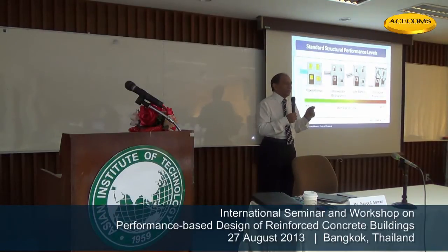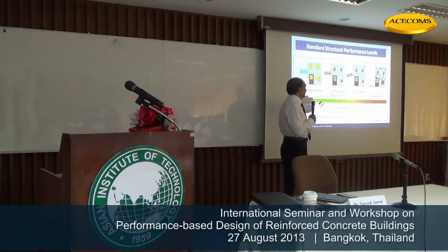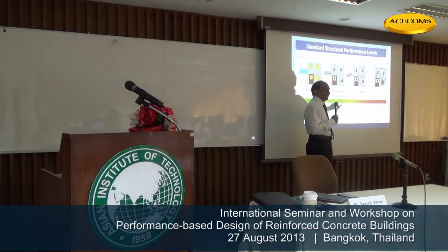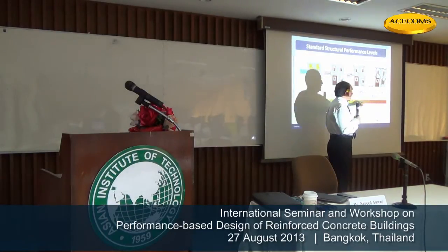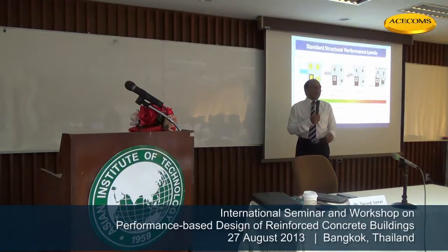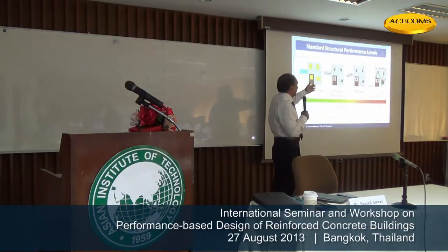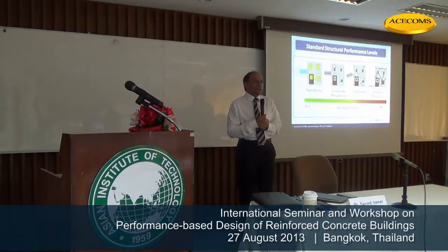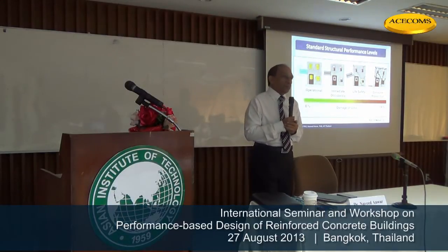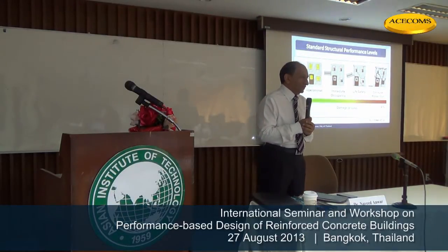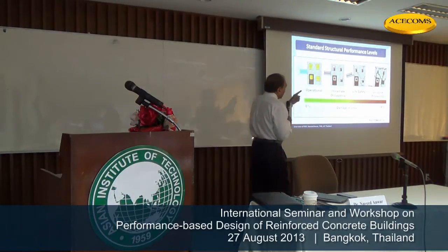After talking about the earthquake a little bit, and then immediate occupancy, we continue from there. Then life safety. That means the building is badly damaged, you probably cannot come in. The lights are all out now, the signboard is falling down, right? You can't use the building anymore after the earthquake, but you were safe. Nobody got hurt, right? Collapse prevention.